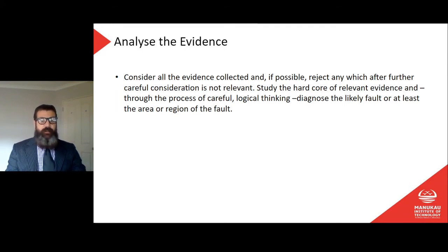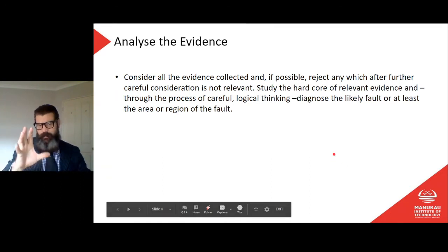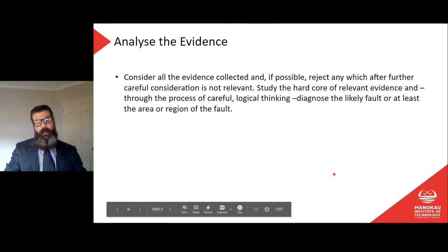Okay, analyze the evidence. Consider all the evidence collected and, if possible, reject any which after further careful consideration is not relevant. Study the hard core of relevant evidence and, through the process of careful logical thinking, diagnose the likely fault, or at least the area or region of the fault. Yeah, that comes back to what I was just saying. Be logical about this, team. Be ruthlessly logical about it. Guessing will very rarely help you and often get you in trouble.